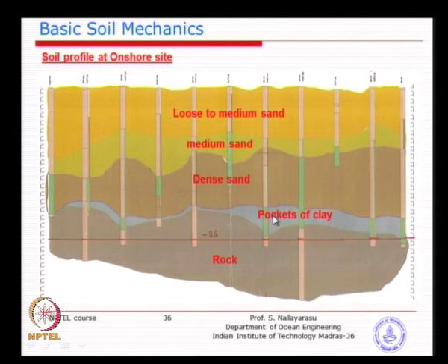So, that is exactly why we need to do more boreholes, because if you have done only one borehole at this location and it happened to be at a location where there is no clay layer, and you think it is representative of the whole site, and construct the foundations everywhere and terminate the pile foundation at that level, then you will end up with lower capacity than what you actually predicted using the properties derived from one borehole.